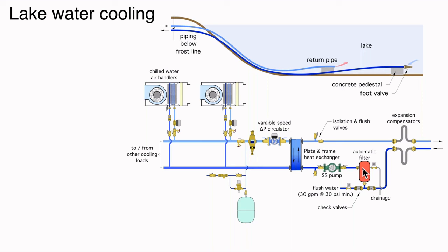So I would certainly look at, if you're contemplating this application, make sure you have an automatic filter that can minimize or hopefully even eliminate any debris from the lake that could get into the heat exchanger.